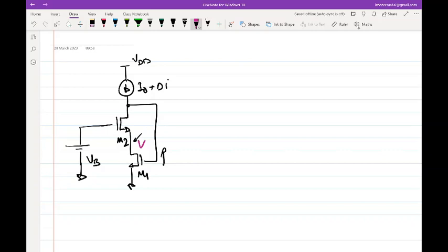But that is a consequence of something happening. That is not the cause, that is the effect. And the effect is happening because if there is a change of I0, the VG of M1 increases. Since the VG of M1 increases, the current through the transistor stack also balances and increases. And because of that, the source of M2 changes. Okay. So that is the argument.